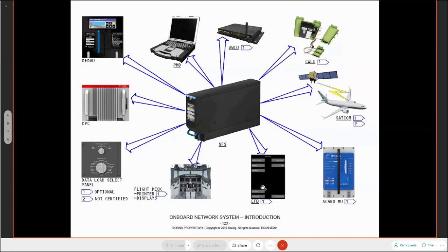We also have the option for the permanent fixed electronic flight bag. These are touchscreen if you have them. Not seen many MAX aircraft with these fixed EFBs. A lot of airlines, I guess, are using the portable EFBs now, which you can probably get on these iPads and such like. But the option is there. The printer, yeah, the printer on the MAX is an option. If you have the printer, then again, the printer will allow you to print off reports that are generated by the network file server.